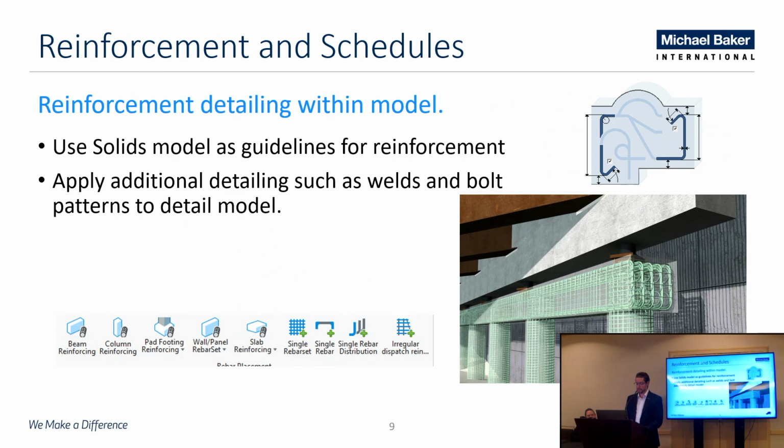So the next step is, once you've got that bridge model built, that solid model built, now you need to detail it. So a couple of those solutions out there, ProStructures, Allplan Engineering, that is the detailing software. That's where you bring that solid element in and you can reference that directly in. Now you've got your shape, and then you can start applying your reinforcement. A lot of the solutions have tools that you can just quickly say, I need this mat up here, I need this mat, and then quickly define that reinforcement, and it'll throw it in there really quickly.